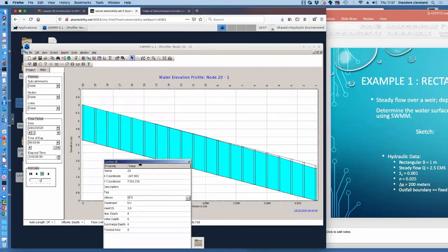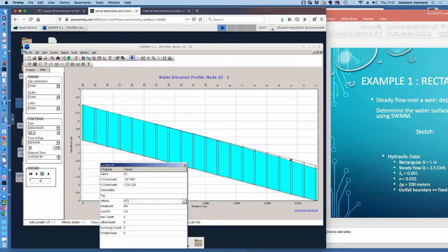And this is actually what I wanted to have happen. What we're visualizing here is that at about junction number 10, the water cannot stay in the channel anymore. So from a drainage engineering perspective, either that channel is not big enough or we're generating too much flow rate.